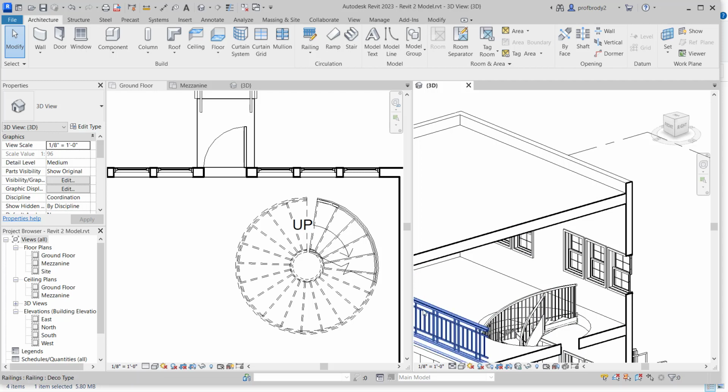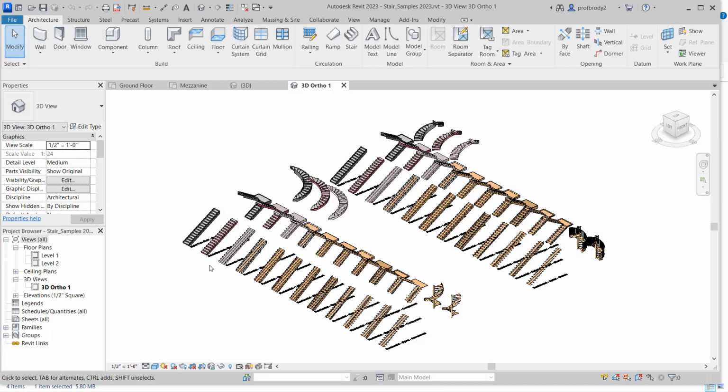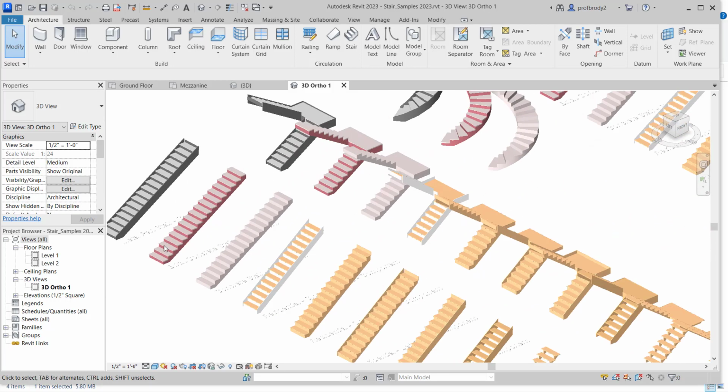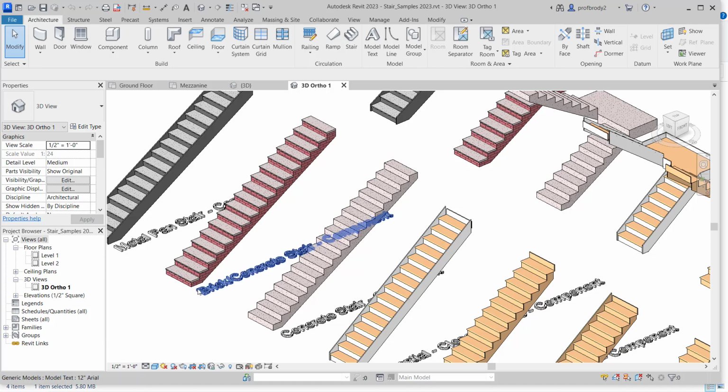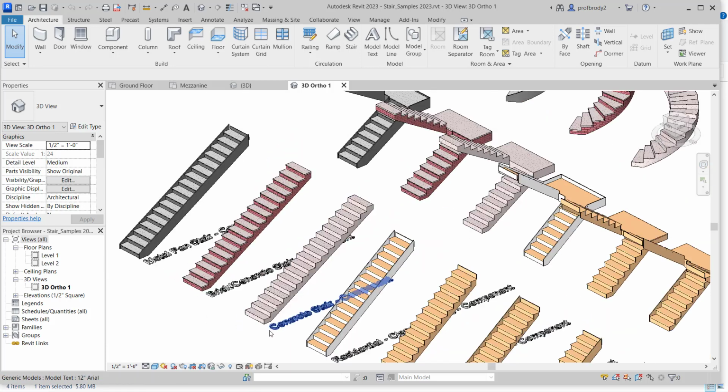I recommend for this sort of thing using a shaft, mainly because you do often have stairs, you have ceilings in addition to the floor. Finally, I should put a railing in up at this opening so that people don't fall through the hole. And I should mention that there is a stair sample file that is provided by Autodesk here, and there's all sorts of different construction techniques.